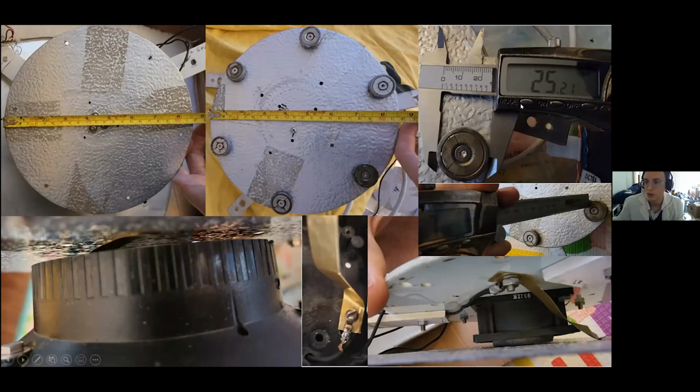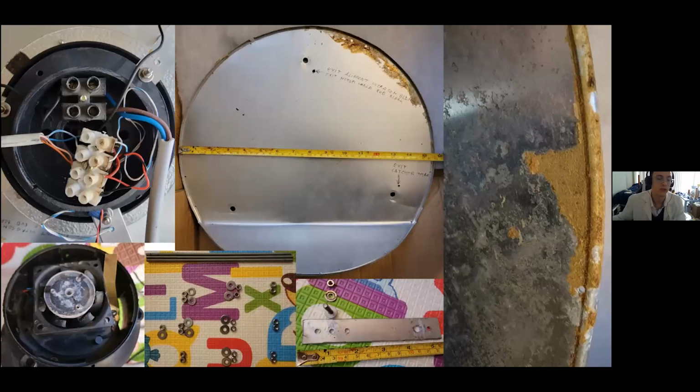Measuring the diameter of those, about 25.21 millimeters, and the height is about 7 millimeters. And the brushes make contact with the outer sides of the plates away from the center plate. They're connected with this brass brush. So this is for the bottom plate and this is for the top. And it just has a lug connected to that runs along the side of the frame. It's for the high voltage.